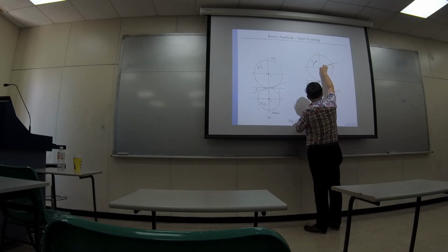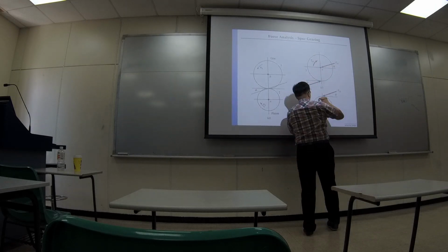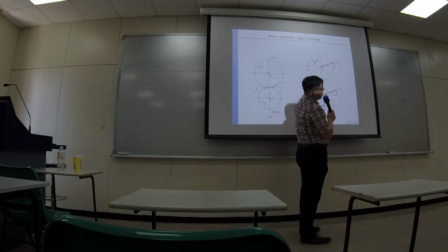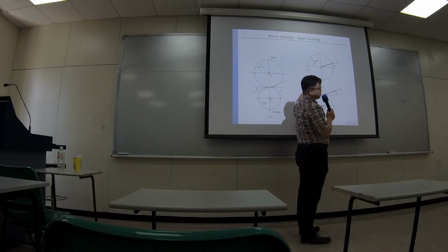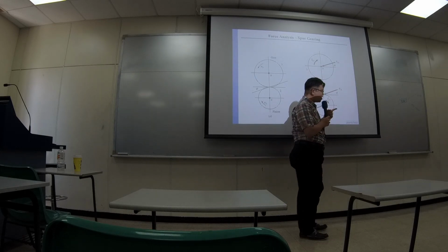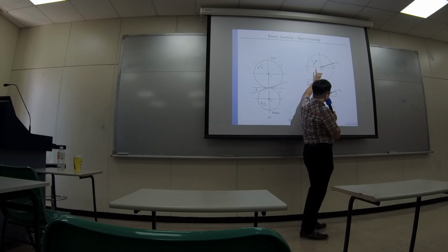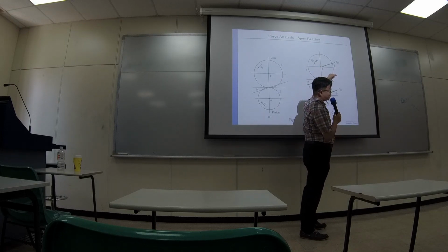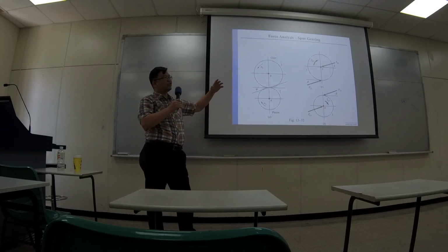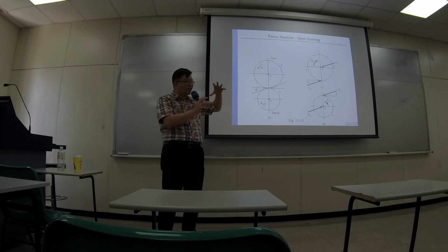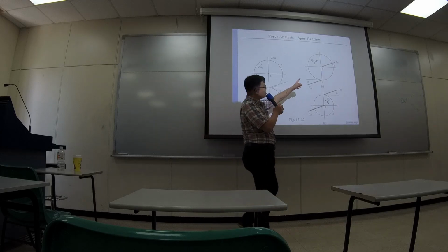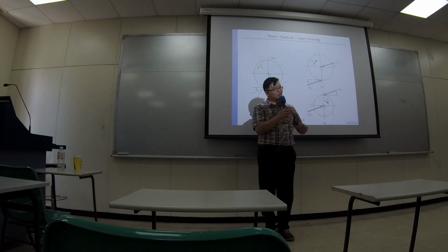So right on the shaft, it's going to generate a clockwise reaction torque to balance with the external force. So on the shaft itself, not only is there a reaction force, there's also a reaction torque. Okay? So think about what we learned in the very beginning. We have a shaft system. If there's a gear, it not only needs to carry the force, it also generates torque.